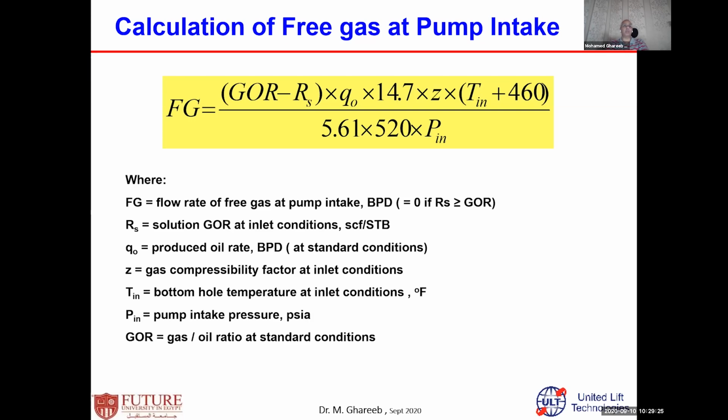And based on that volume, you see what type of pump I need, what type of configuration I need. Do I need a gas separator? Do I need a good venting efficiency at the surface? What will be my wellhead pressure? Because venting efficiency means the gas going to the casing and venting to the surface, against what pressures and so on. This is just for your reference.